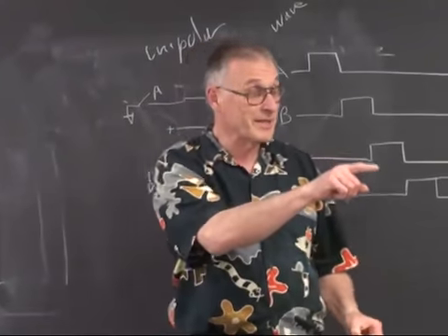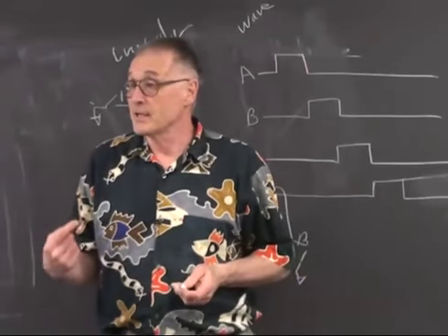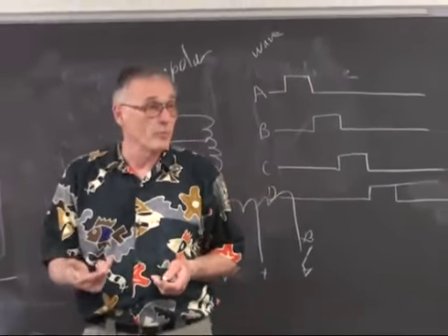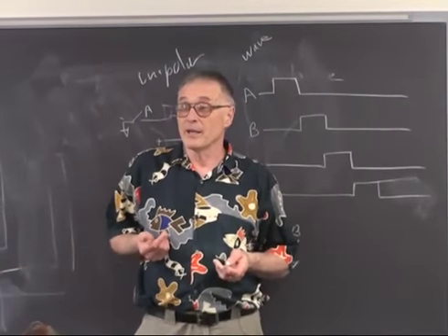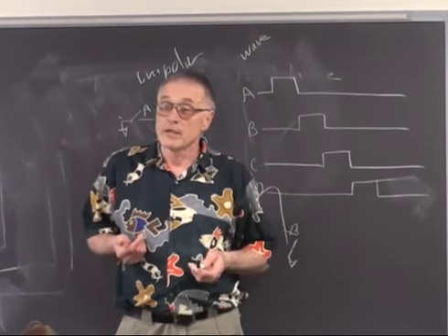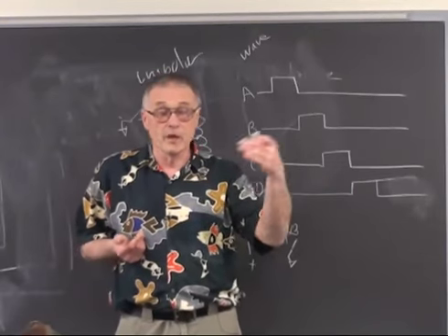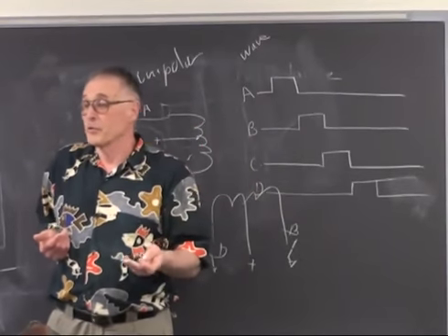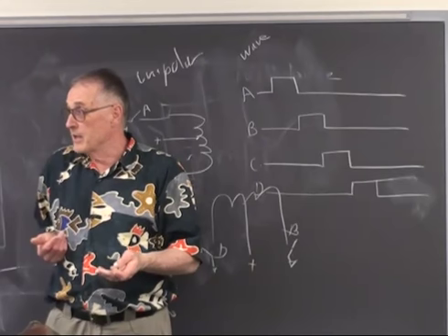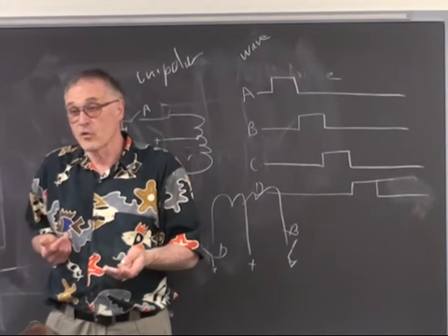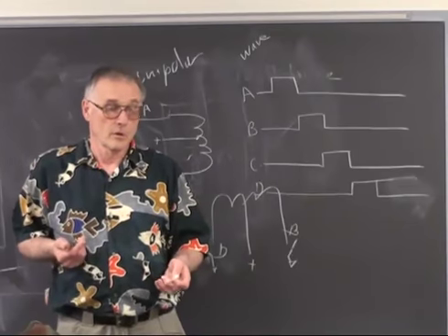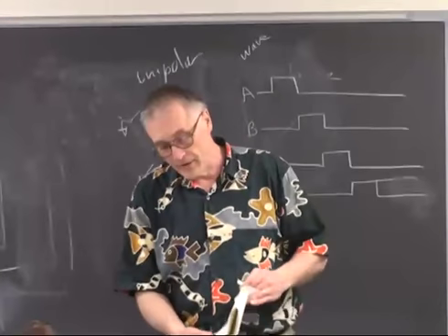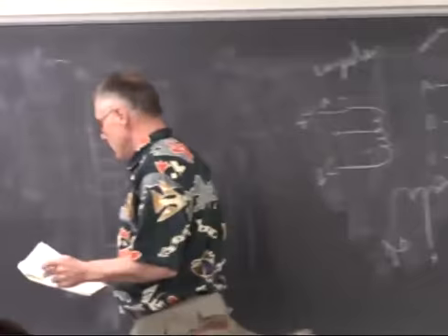That's a good point. And my next few sentences are going to be that you don't have to do the pulse generation yourself even. You can buy integrated circuits that will take a command like run forward, run back, plus a few lines for speed, and the high-level controller will take care of all of the pulse sequencing for you. So you don't have to roll it yourself.